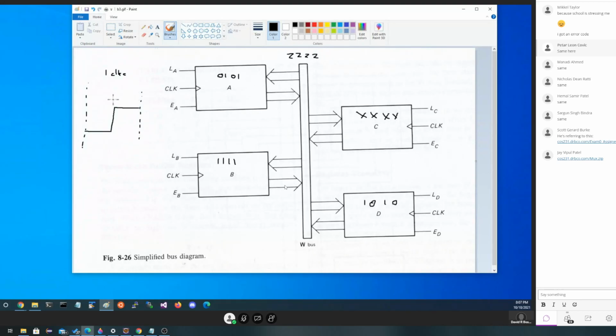So lights, camera, action. What we want to do is we want to move the data that's in A into D. So the moment the clock drops right at this cycle right here, just as soon as it goes low, we have to assert 2 signals. We want A to write. We want D to read. What signal do I need to assert for A? Raise your hand if you can tell me. Robert? Enable. So at this point, enable A gets asserted. And somebody else tell me what signal gets asserted on D.